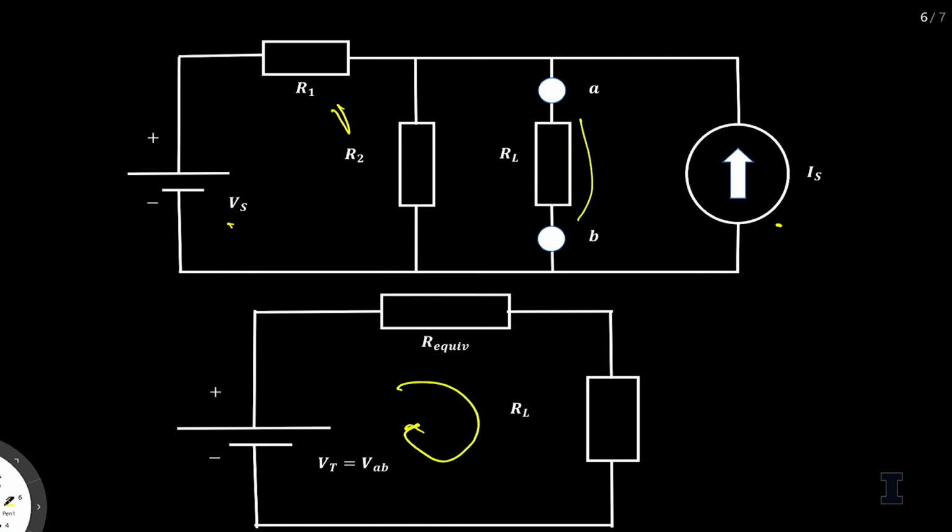Remember that we use Ohm's law to analyze these. We have the Thevenin voltage, we have the short current, and we have the equivalent resistance. So if at any time you have two of the three elements calculated, you can remember that you can put, as in this example, the Thevenin voltage over our equivalent resistance to get our short current. Through this exercise and example, we've taken a complicated circuit, as shown through the steps, and simplified it to a simpler model by which we can understand these parameters and what's actually happening in the circuit.